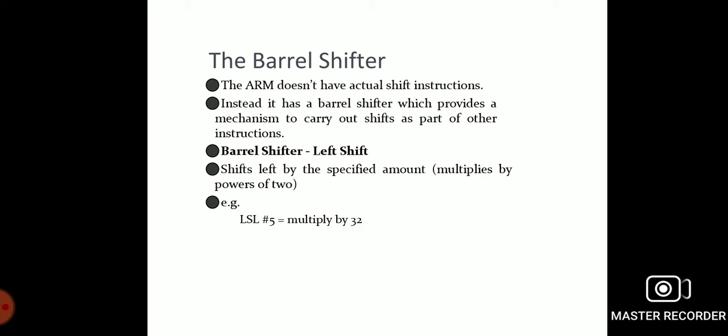So the arithmetic shift right and arithmetic shift left divide or multiply by a power of 2. It preserves the sign bit, for the sign bit shifted in, in 2's complement. And also the arithmetic instructions, that is add the 32-bit value with carry.